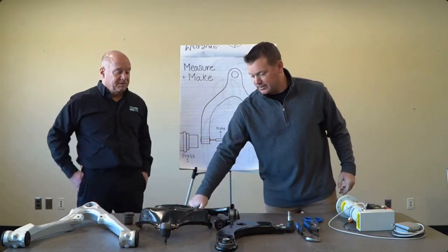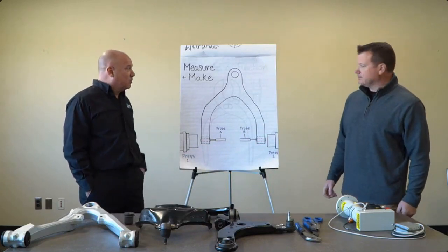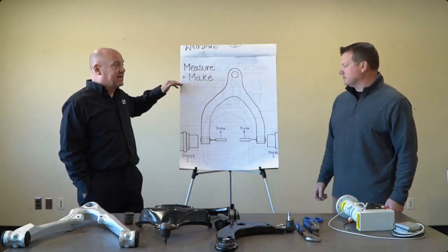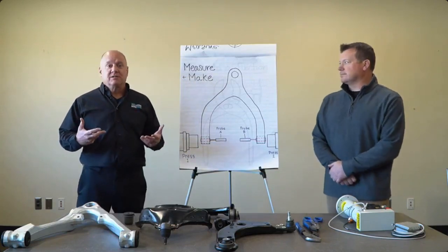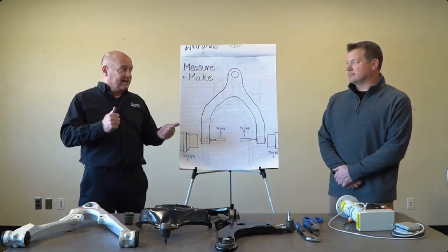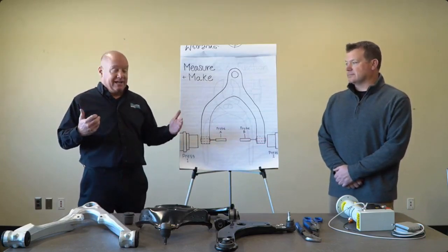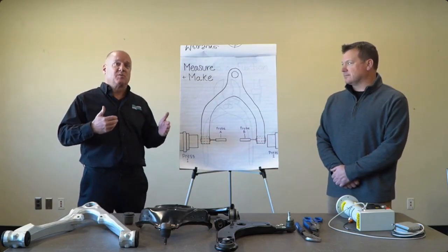So exactly. That's an example of what we call measure and make and measure. We're actually measuring the critical dimensions of the part as we're assembling it with either digital or analog probes, taking that information back and using it to control the presses as we're making the parts.